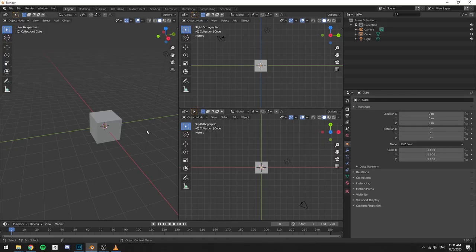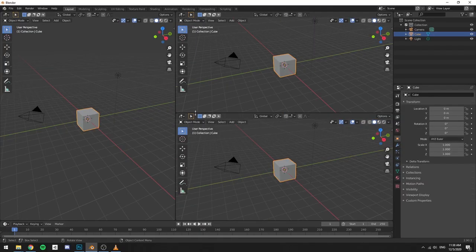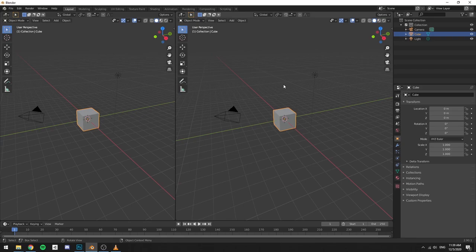So this is pretty handy and pretty useful to create such modularity and just to create your best layout. So guys, if you want to close these windows, it's pretty easy. Go to the left corner and your mouse cursor will be turning into a crosshair again. Just left click and drag on top of the window above it.